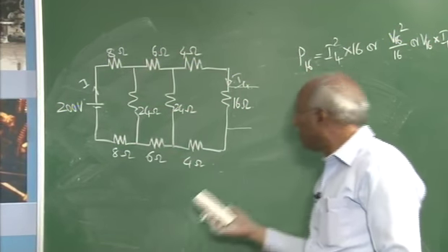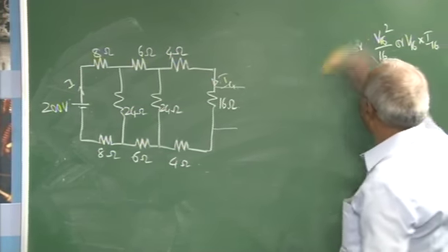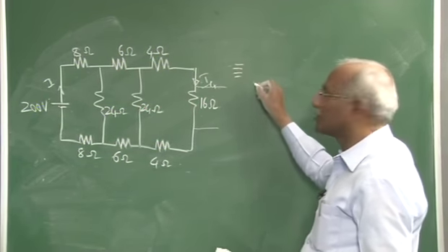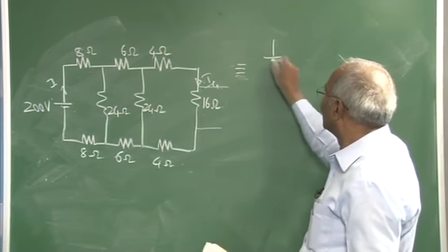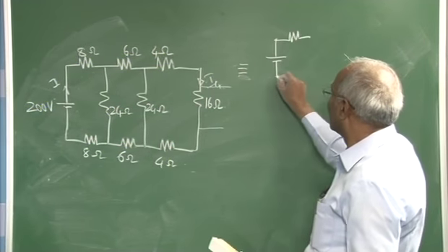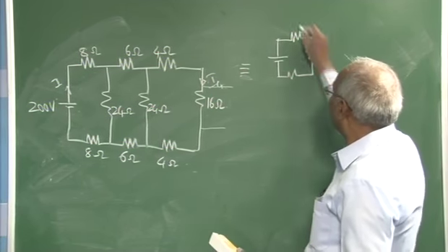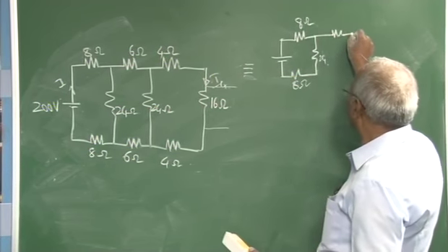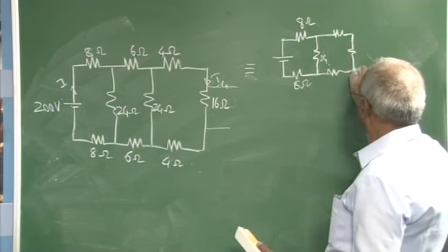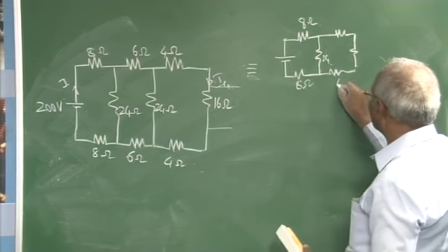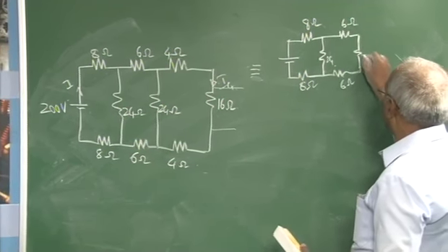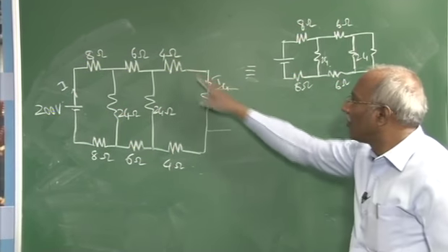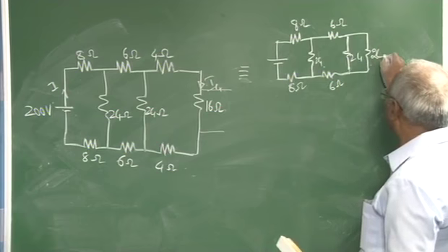Though it can be discussed mentally, or the final value can be arrived at, it has to be shown how to reduce this. In that respect, you can see here, this is 8 ohm, this is 24, this is 6 ohm, 24. We can go for one more resistor, this is nothing but 4, 16, 4, that comes to 24 ohm.